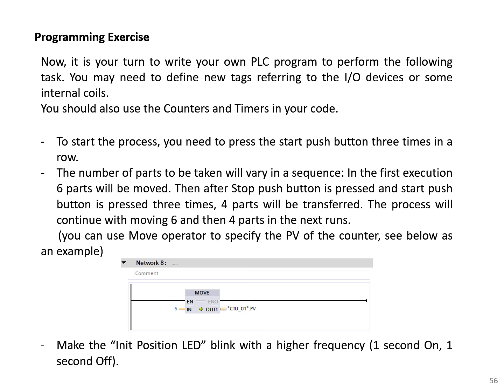Every time this move box is enabled, the in value will be transferred to the out value, and the out value is the preset time.